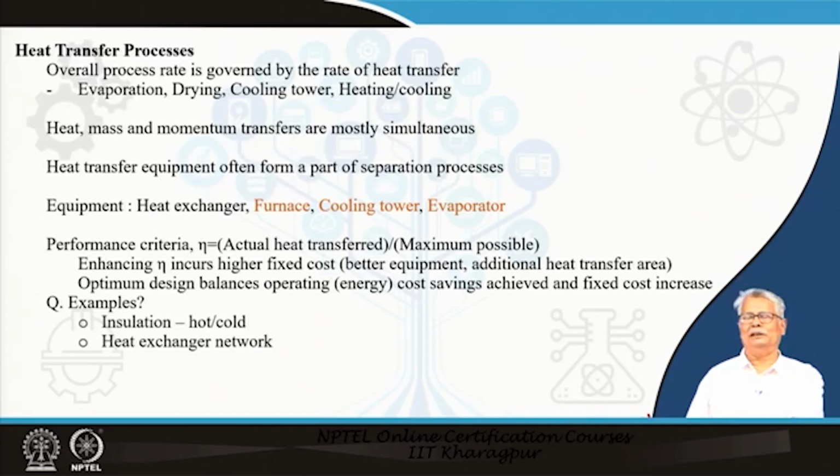An example of this could be, if you talk about distillation, on the tray you have movement of the liquid, which is definitely a mass transfer process, and you got to design your tray based on the tray hydraulics, which is basically a momentum transfer process. The mass transfer decides the number of stages required, or the enrichment or the efficiency on the tray, and definitely the vapor coming in and the liquid coming in from the top, they are mixing on this, but they come at different temperatures. So, there is heat transfer as well.